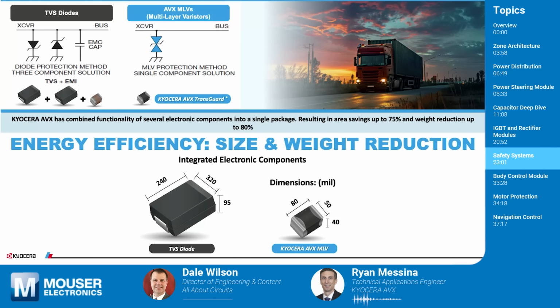The whole dielectric, essentially the whole area of the MLV, will absorb the strike, whereas when you're talking about a TVS diode, you just have one small PN junction, or if it's a bidirectional diode, you've got two separate die that have a PN junction that will absorb the strike, and it's not a lot of real estate to absorb it. So the wear out mechanism is going to wear out much faster.